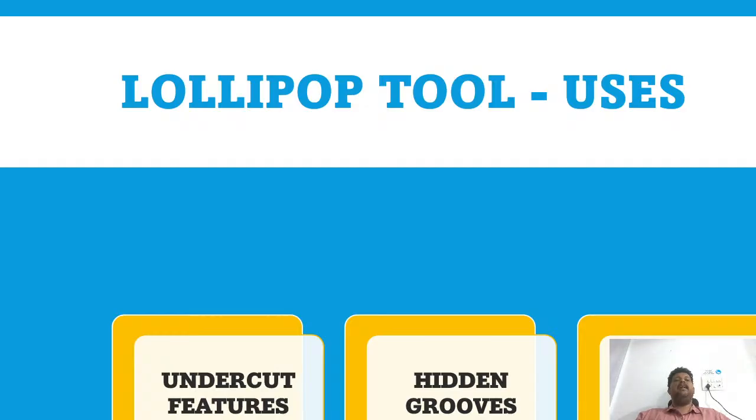Now, let's see where this tool is actually used. This is where things become very clear. Lollipop tools are mainly used in situations where the cutting area is not directly visible or accessible from the top. For example, in mold and die components, you often get small undercuts or reverse curves. In parts like impellers or turbine blades, there are complex shapes where the surface goes inward. In such cases, a normal tool can only reach the outer surface, but the inner or hidden portion remains unmachined. This is exactly where the lollipop tool is used.